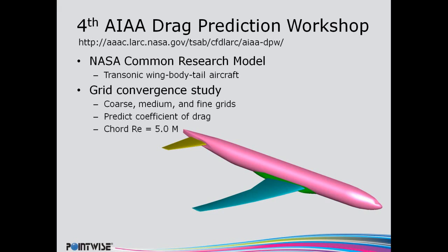That's what the script we're going to be demoing today is concerned with: being able to create the family of grids that's necessary for a grid convergence study, because essentially we just want to look at the effect of the increase in resolution while trying to maintain the same or very similar character throughout the increasing resolution of grids.